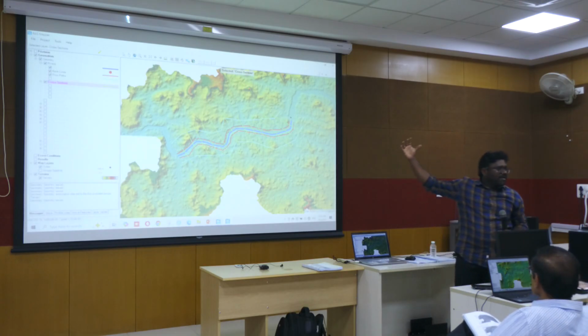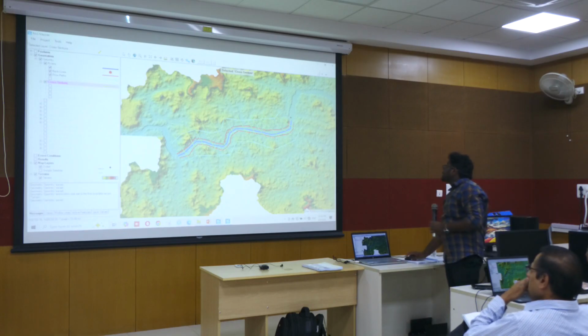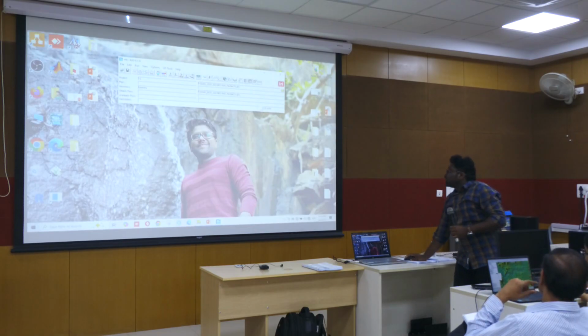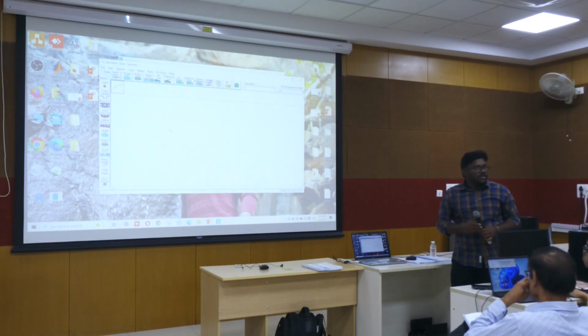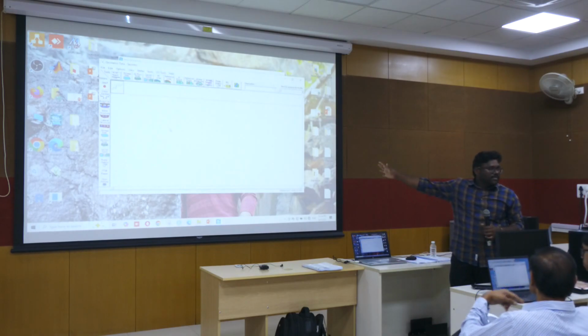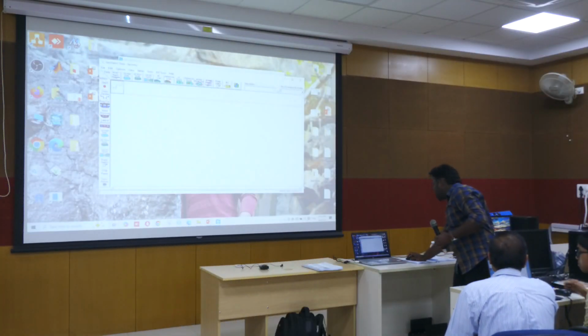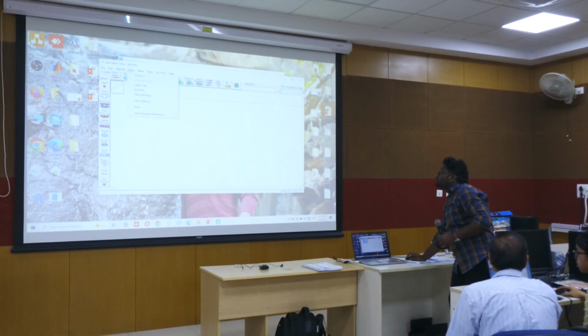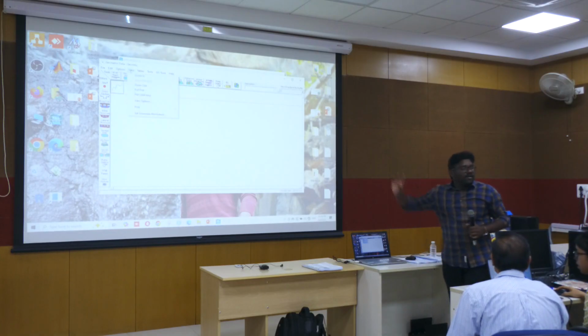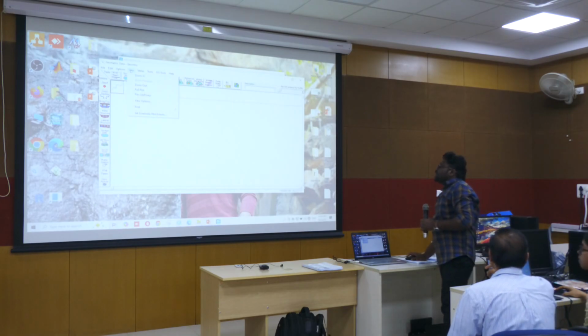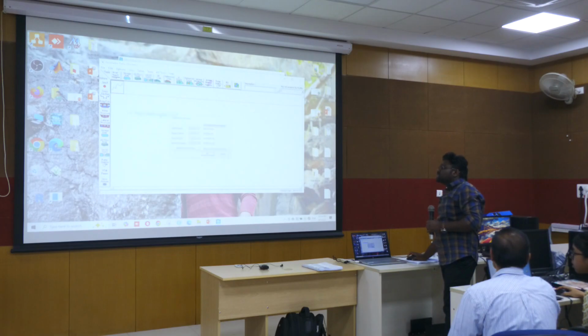Now automatically the model will take this geometry into the geometry file. Just close this. Go to edit. Click on geometry data. Here all those cross sections will be visible. For that you need to do one step. Click on view. Click on set schematic plot extents.